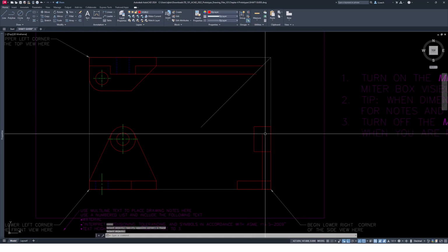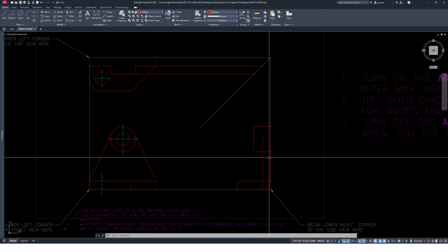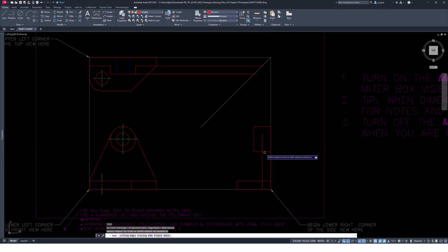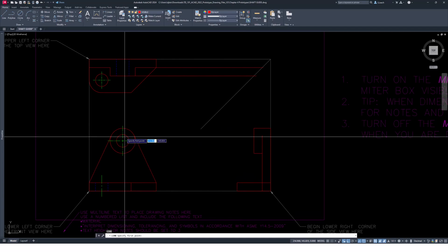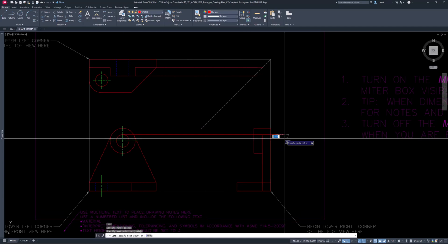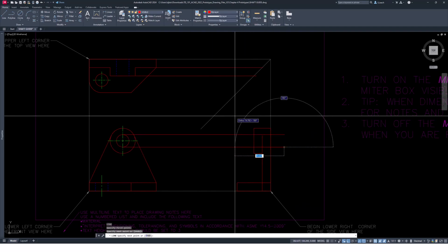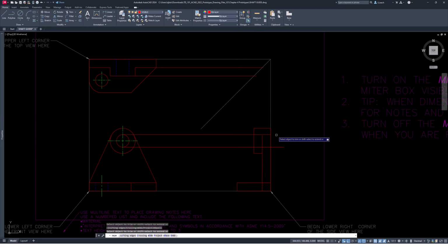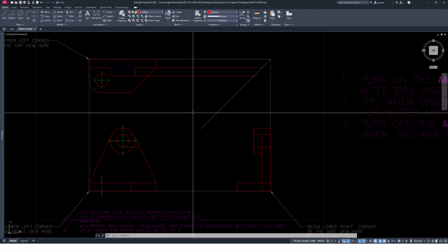There's not an actual line that goes across, because that all curves around. Trim this out. And then I'm going to project this inside quadrant of the circle over. It goes all the way through. I'm going to trim these out. So if you notice, usually in my drawings I use line, offset, trim, extend, fillet. I use those commands over and over again.